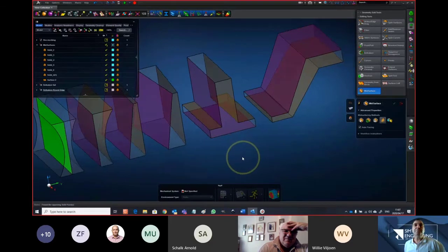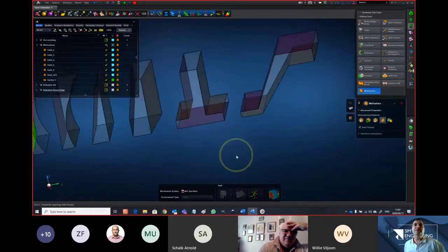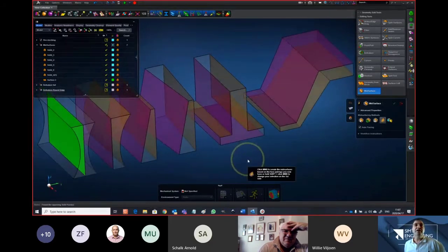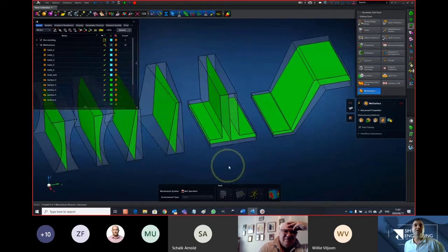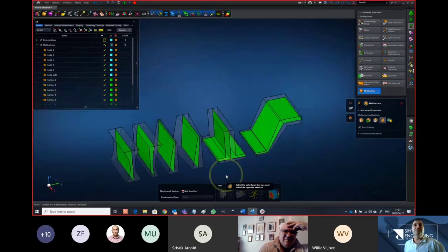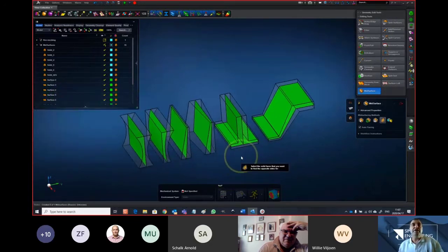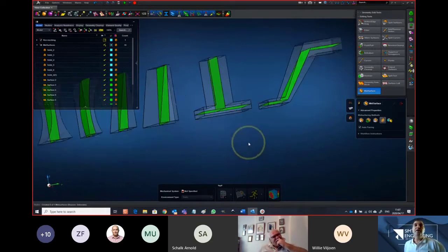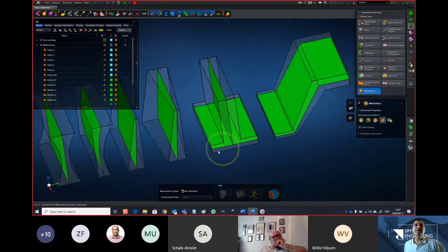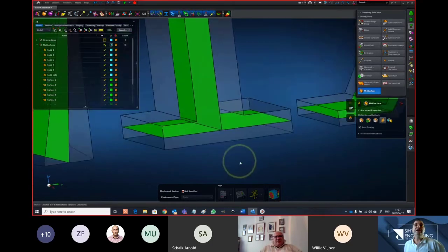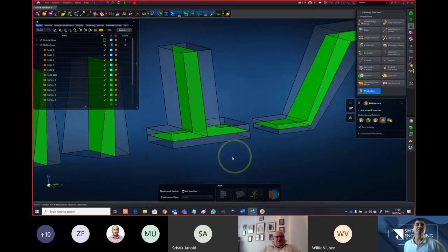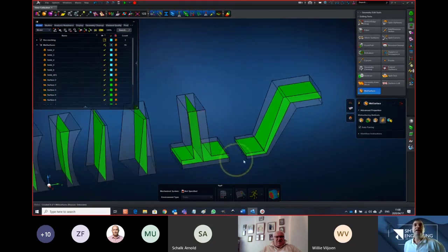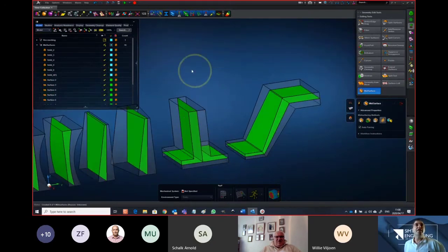In the next step, it will show you the pairs or the pair elements. And then in the last step, it creates your mid-surface. So this is a very useful tool specifically for varying thickness solids or more complex elements like these, where there's T-sections where the interfaces, or the mid-surfaces, should actually be extended to intersect.